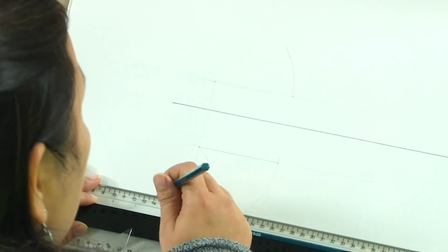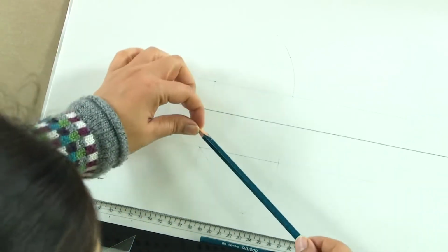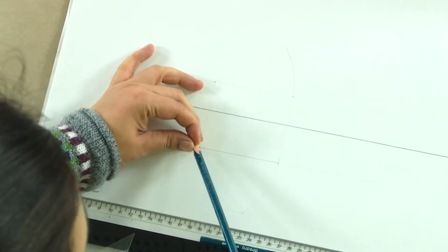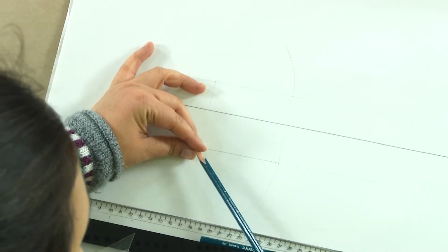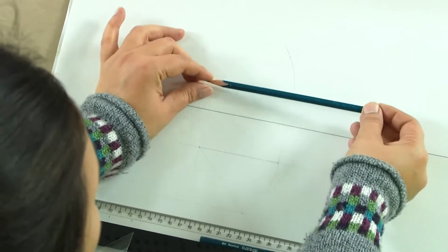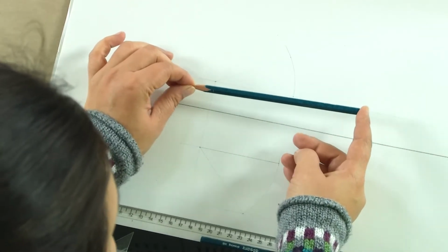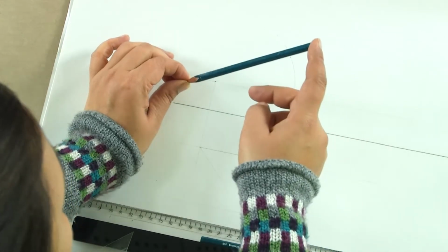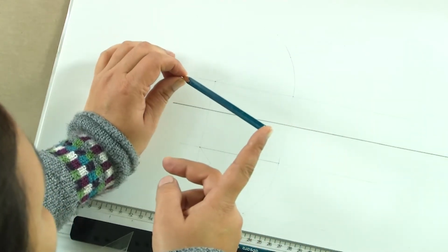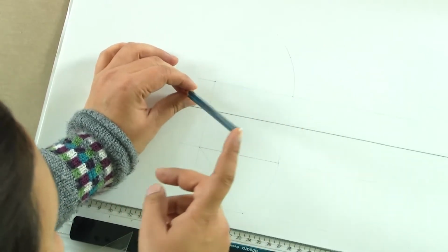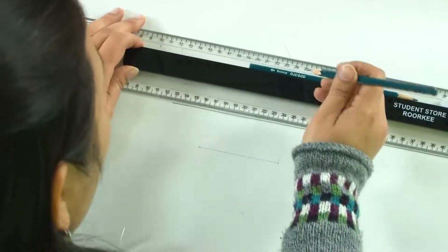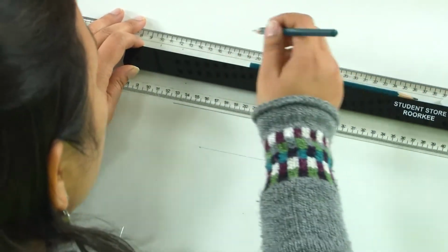Now, if you remember when I was explaining the movement of the line, we said that if it is inclined to one plane and is inclined to the other plane as well, this is how, in a conical manner, the line will move. Similarly, if it was inclined to HP at an angle of 30 degrees, to make it at an angle of 45 degrees with VP, we will have to incline it in a conical manner such that the top point maintains its distance from the horizontal plane and the vertical plane.